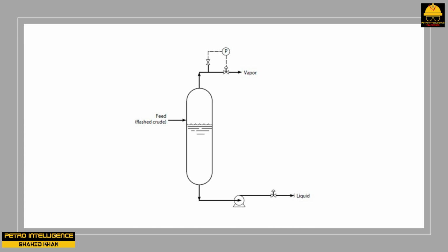But this will take time. If the residence time of the liquid in the drum is 10 minutes, then it will take 10 minutes for the lighter liquid to reach the suction of the pump. During this 10-minute interval, the liquid flowing into the pump is the older, heavier composition. If he raises the pressure in the drum suddenly by 5 psi, this instantly supplies about 20 feet of additional available NPSH, but only for a period of less than 10 minutes.